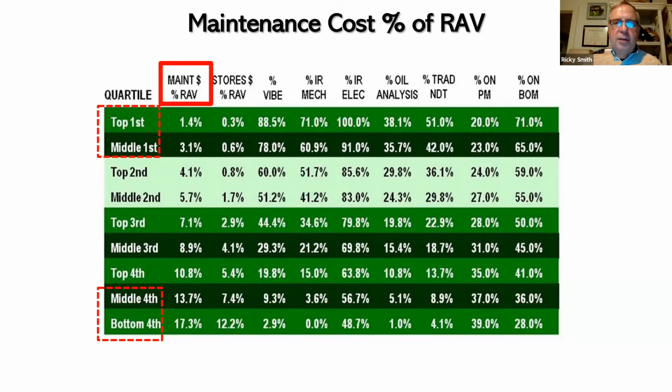All right, what else? Bottom line is fix it right, it lasts long. Yes. Do most companies work with hour-based PMs or calendar-based PMs? Most of them are calendar-based. My personal preference, when I'm maintenance supervisor, maintenance manager, I like doing it by hour, by day, so the PMs were done on time. But I'd say 98% or 99% of the companies I've worked with over the years, it's based on day, not based on hours. It's calendar based.